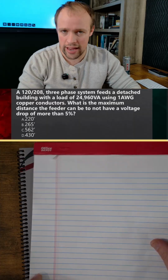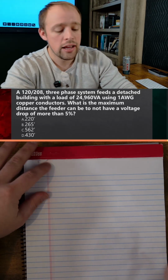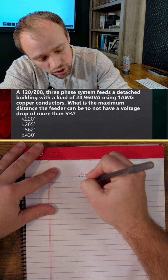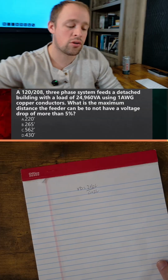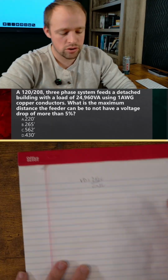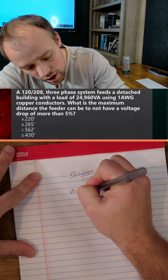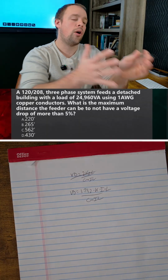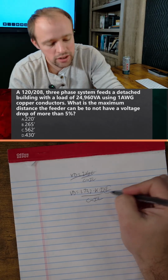You can't find the answer in that, but I do cover this topic in chapters 4 and 2 of our book, A Comprehensive Guide. The formula that you need to know is voltage drop equals 2KIL over the circular mills of our conductor. However, this question specifies that it's three-phase. Anytime you see three-phase, we replace our 2 with 1.732. So voltage drop equals 1.732 times K times I times L over the circular mills of our wire. However, the question asks for the maximum distance, so we need to solve for L.